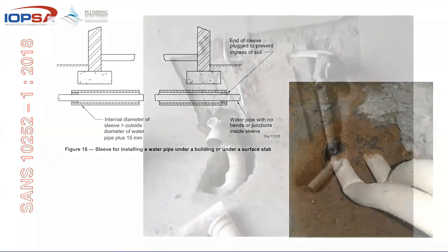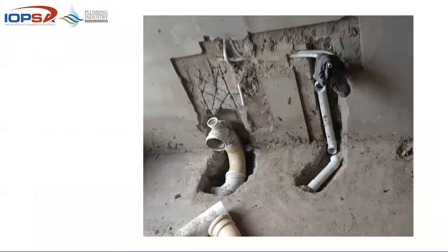And then unfortunately, the same rules apply to drainage. It's not always adhered to, but here you can see a typical example of no change of direction in the floor. So you can imagine what a nice maintenance job that's going to end up being, going through 1, 2, 3 90-degree bends in one WC installation. Same thing with these waste pipes. So you see the requirements speak to each other. 10.400 part J speaks to floors. It refers to other requirements.